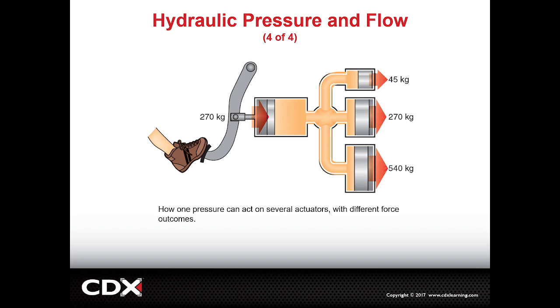Where is it useful to come up with the force factor? Let's take this easy one here. A factor of 2 can be applied in other situations when you are just looking at a situation and you have a force factor of 2 to 1, let's say, and you are applying an input. This is just off the top of my head. You're creating an input force of, let's say, 5,000 pounds. What's going to be your output if you have a 2 to 1 force factor? Your output force is going to be 10,000 pounds because it's twice the input.